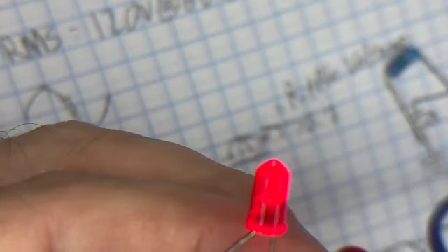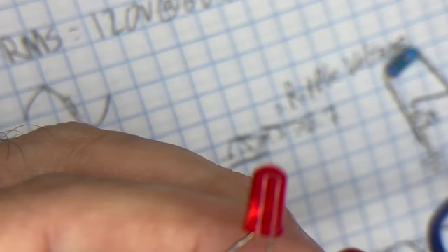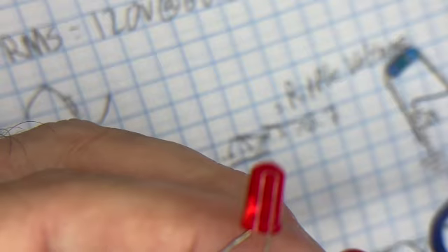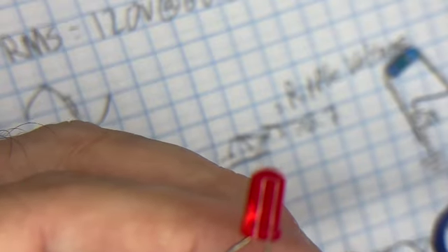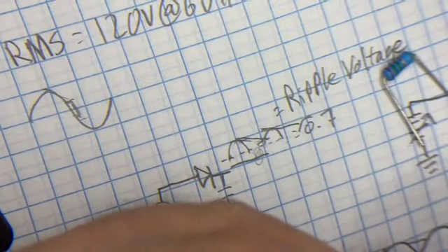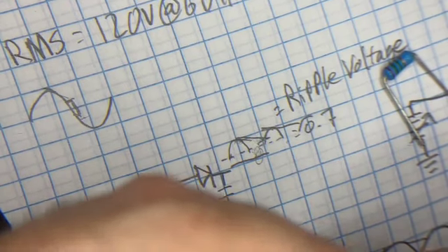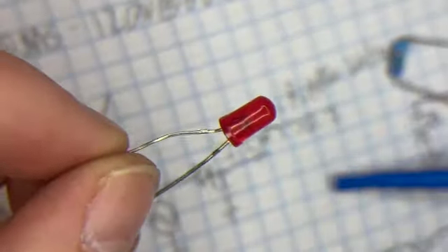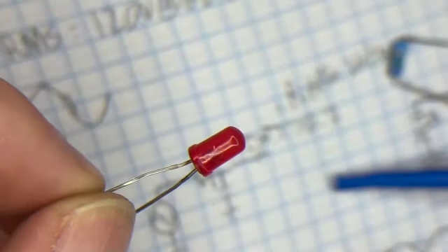Eventually, what's going to happen is this diode is going to burn out. Right there. 2.5 volts. So this diode, I just ruined it for your benefit. At 2.2 volts, it got 150 milliamps going through it, which is too much for this thing to handle. Typically what we would do with these is hook up some kind of current limiting resistor that we can actually calculate using Ohm's law.